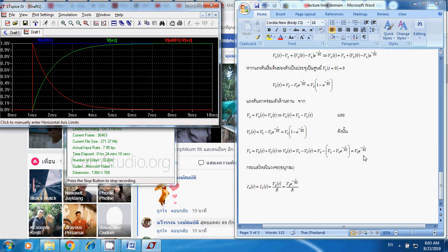And then following the expression here, Vs multiplied by exponential negative t over RC, when the time increases, this term is getting smaller, right? So that means you have Vs multiplied by a smaller term. So finally it drops, because when the time goes to very large, this drops to 0. So it exactly follows the expression of your voltage across the resistor. Okay.